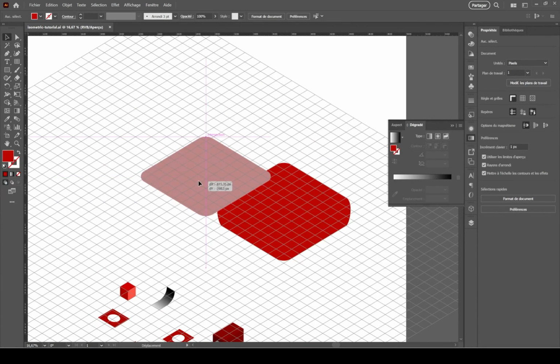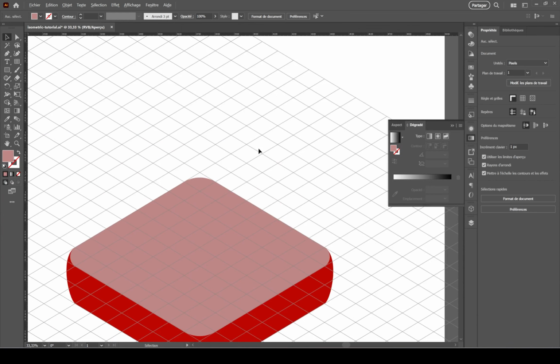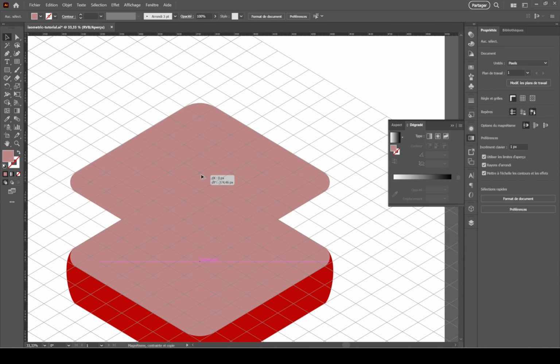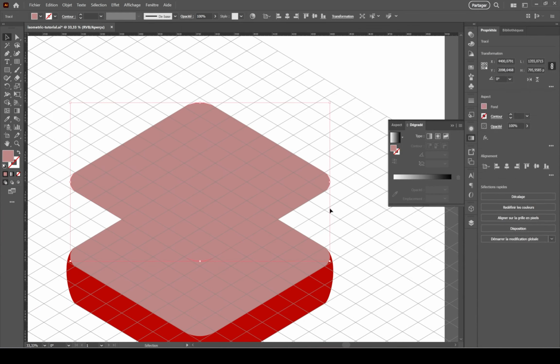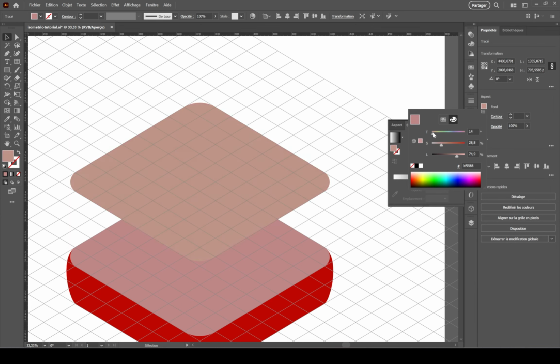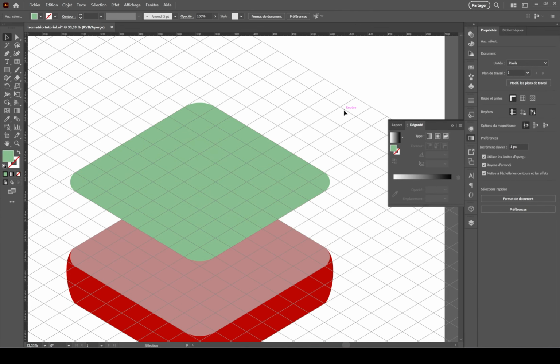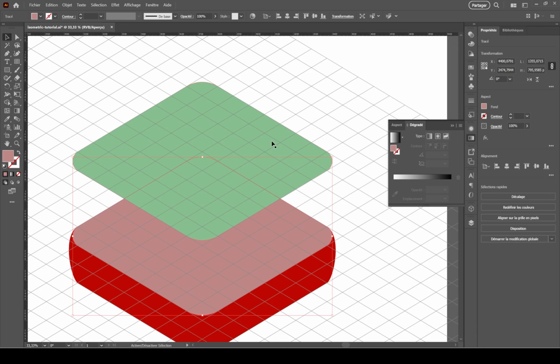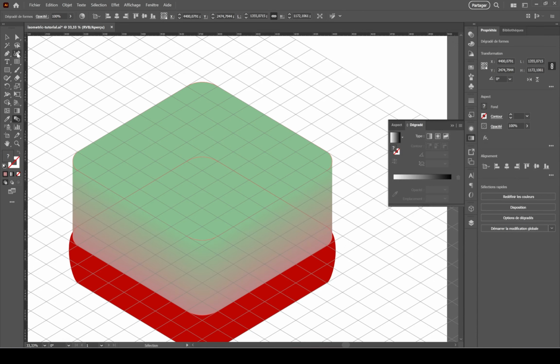For the next technique, I will simply use a shape gradient, very cool tool for isometric design. You can build a lot with it. For your 2 shapes, use your shape gradient tool. If you don't get good results, double click on the gradient tool and set it to steps and increase the number of steps.